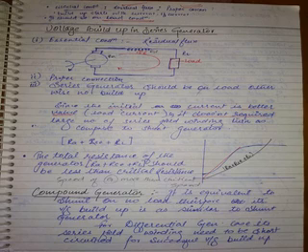Because if the machine is on no load, across the terminals if there is no load, no current will flow into that. So the series generator should be started. If you want the voltage to build up, then you have to connect some load across it. Loading means what? Loading across those two terminals means you are reducing the resistance across those two terminals. Yes or no? You are reducing the resistance across those two terminals, which means you are increasing the current actually. You are making the current increase in that particular path.